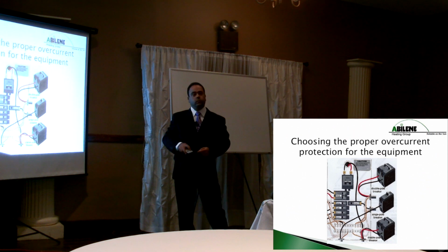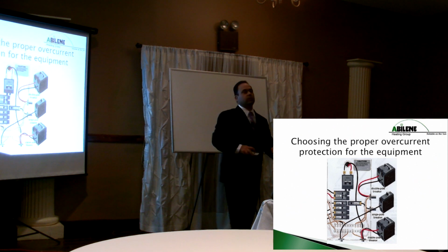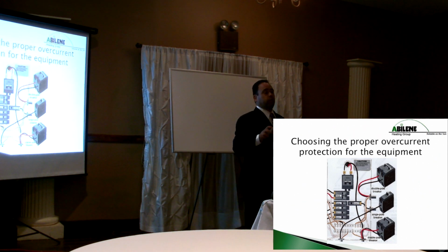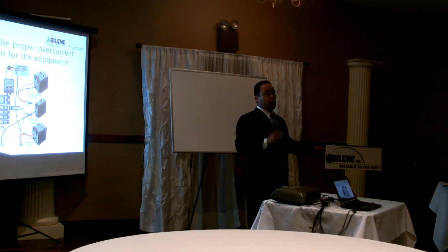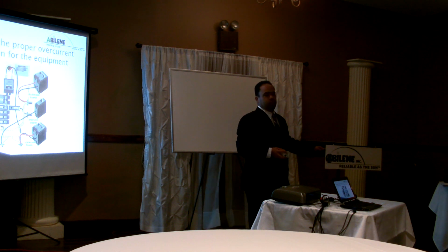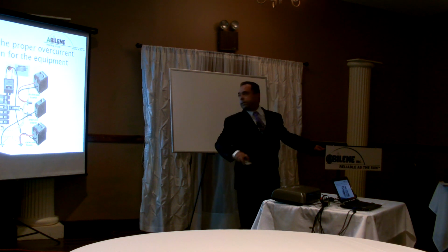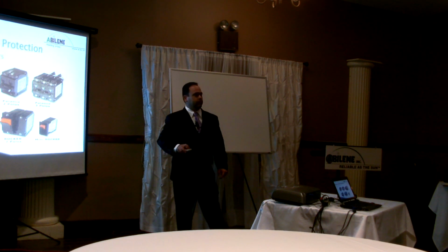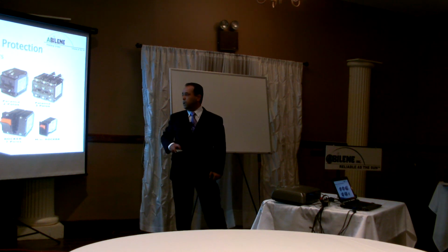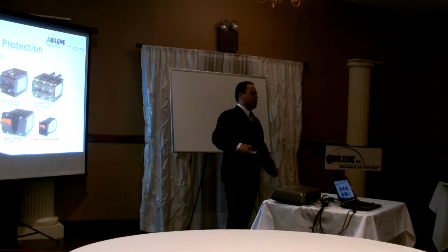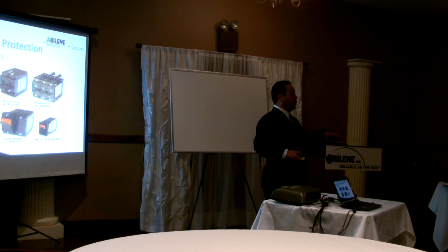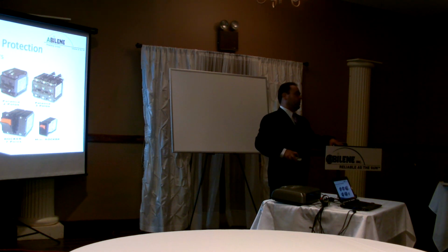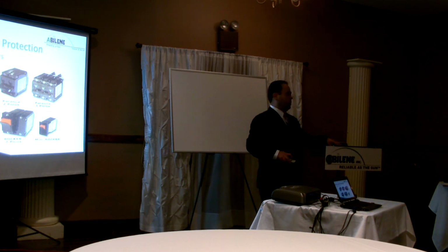In other words, one is a high range, one is a low range. They're different ratings of short current ampacity. Electricians will see it. Most of us won't even look at it. It is no good. It's sized wrong. It's sized okay for overcurrent protection, but not for short current.